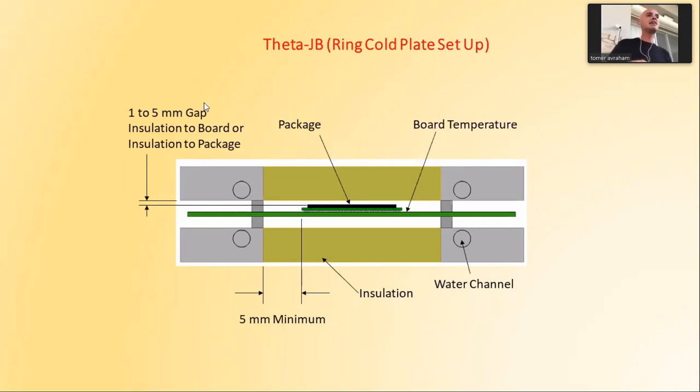Here you see the test done for achieving theta JB, the thermal resistance from the junction to the board. Being properly set up, the board is here, the water channel here, everything is written.